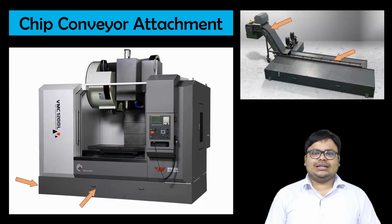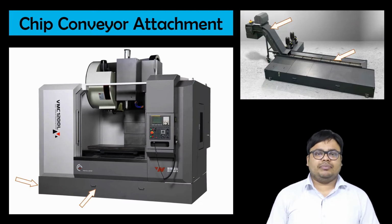Then moving on to the next one, along with the coolant tank, sometimes we also get the chip conveyor attachment. During the operation of the CNC milling machine, when operations are continuously going on and chips are coming out of the workpiece, there is no need to stop the machine or stop the cycle and clean the chips. If this conveyor is there, it will automatically take all the chips from inside the machine to the outside. This attachment is known as the chip conveyor attachment.